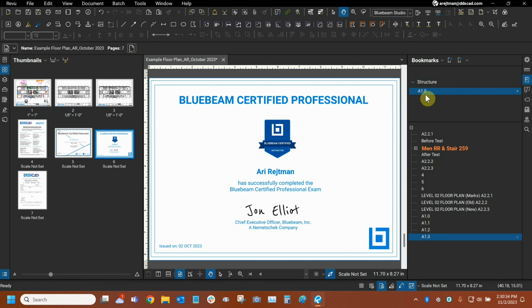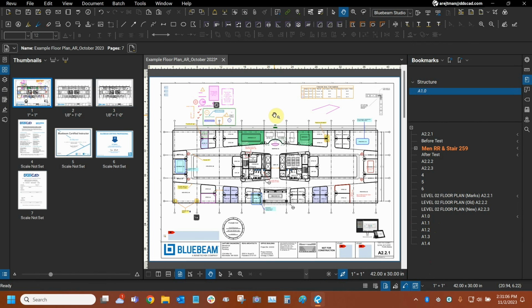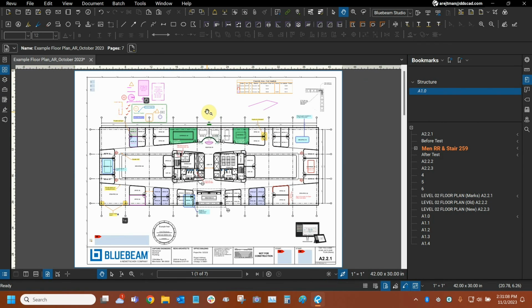This is how you can use these dynamic bookmarks. You don't have to create bookmarks for everything. You don't have to rename them manually. So just that double click motion really, really helps. And just as icing on the cake, I'll do it one more time. There it is. And it's remembering which bookmarks were made this way. So now if you delete a bookmark in the middle, it will cycle back to that previous number. So this is for 1.4. I'm going to click plus. And there it is. We have made plenty of bookmarks quite easily that are now numbering themselves automatically through that dynamic setting. And that is how we can create dynamic bookmarks in a nutshell.